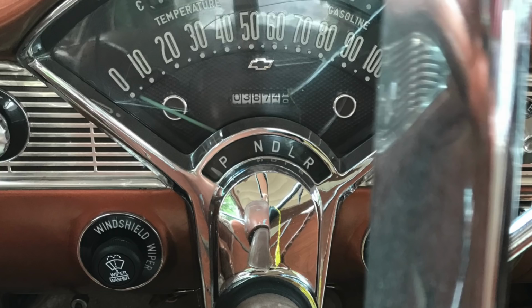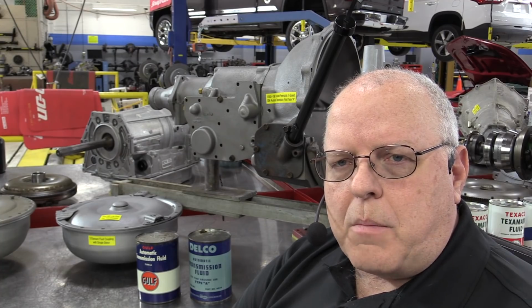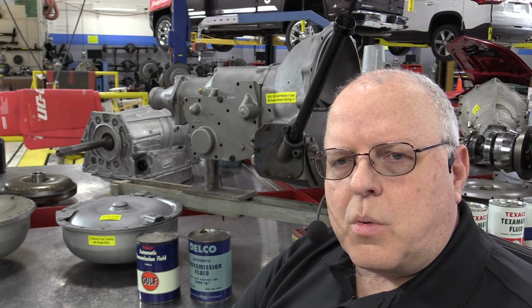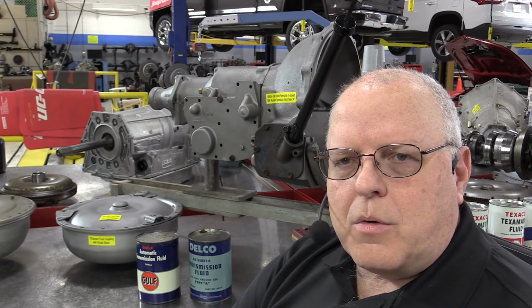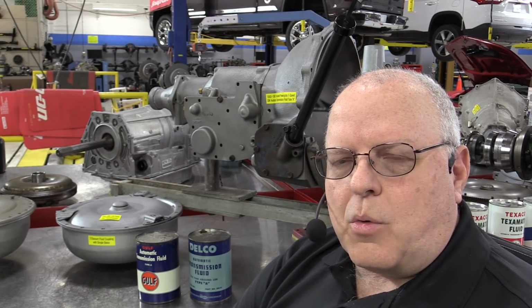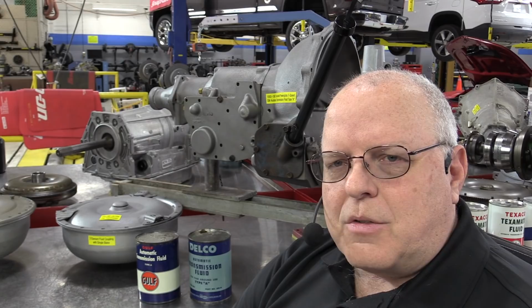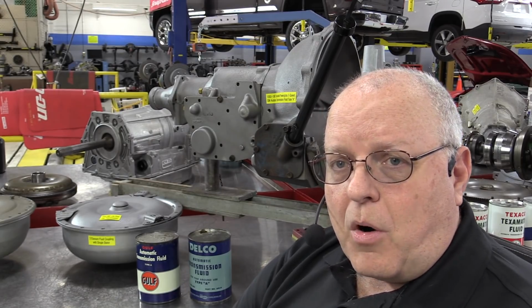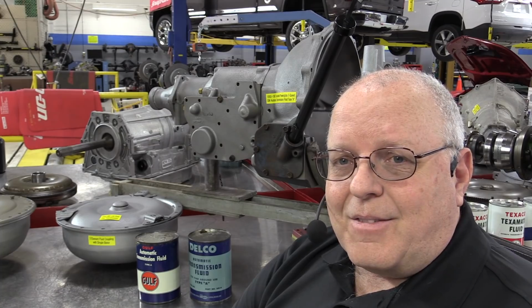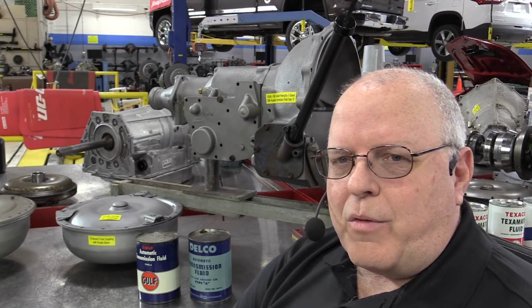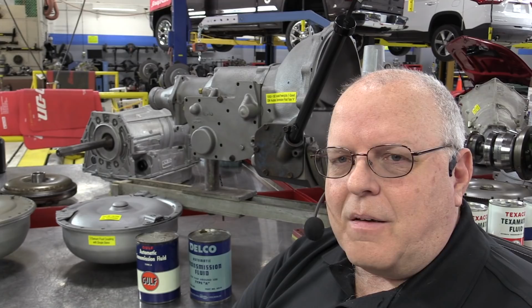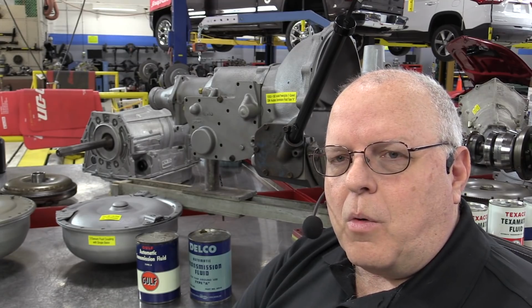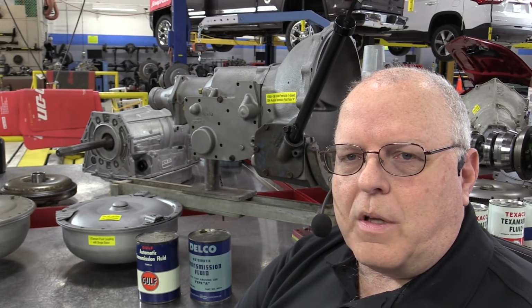One way to get unstuck was to rock the vehicle forward and backwards. Well, these transmissions were designed to rock forward and backwards. That's why they put low right next to reverse. And in the instructions in the owner's manual and the service information, you could actually do a part throttle shift from low to reverse, and back. Today, if you try to do that, the computer will block you out and won't let the shift complete.